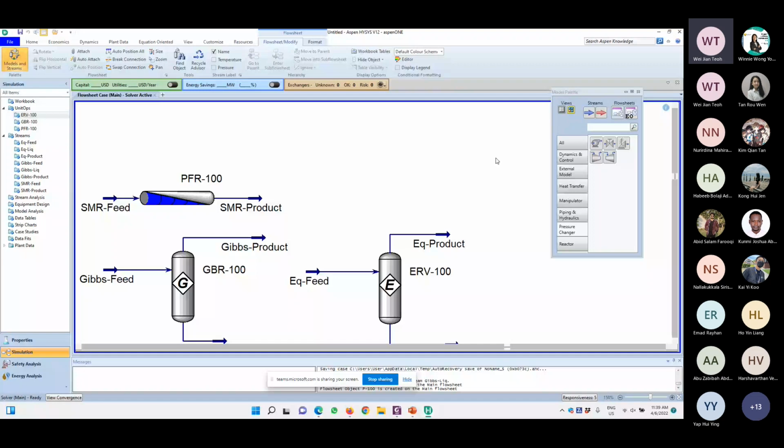So the reboiler duty depends on two things. The first will be the vapor flow in the column, and the second would be the boil-up ratio in the column, which in the ideal situation is the same as the reflux ratio. So you can do that by reducing the reflux ratio or boil-up ratio of the column. If you're using the shortcut method, then reflux and boil-up is the same. So you can reduce that, or you can reduce the vapor flow from the reboiler to the column.